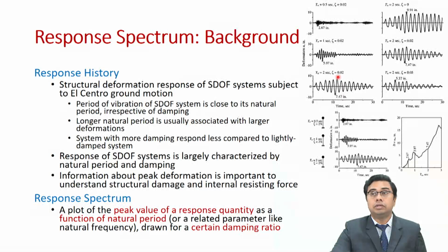Another thing we observe is that as we increase the damping in the system, the systems respond much less. That is, heavily damped systems respond less compared to lightly damped systems. Out of all these observations, what is evident is that the response of a single degree of freedom system is largely characterized by its natural period and damping.